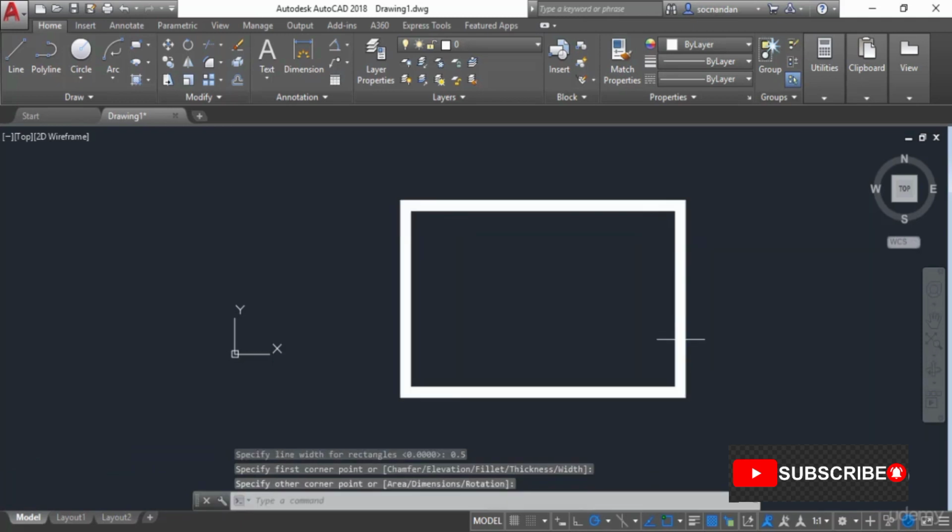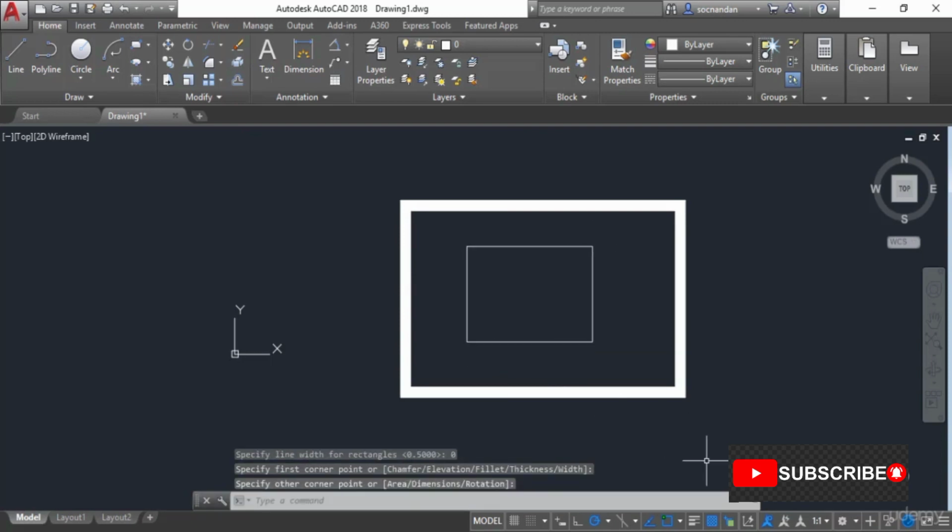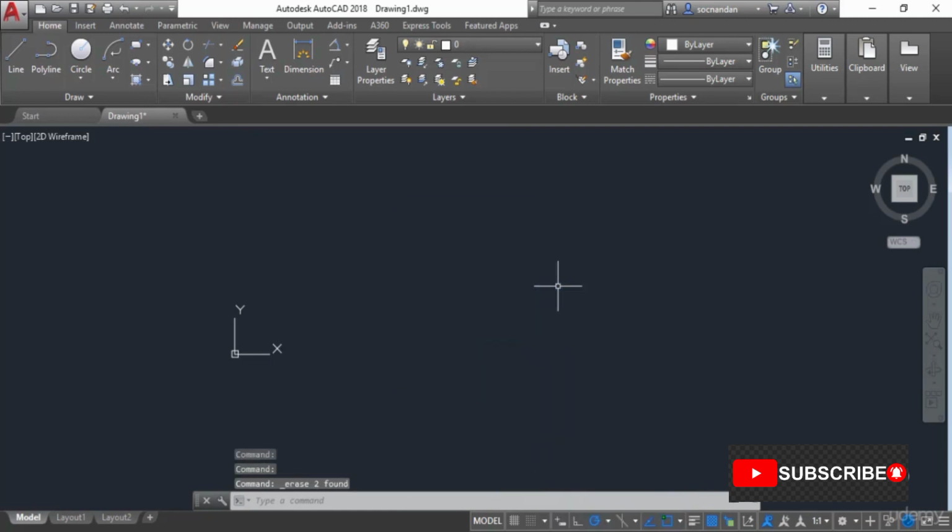And now here we have this rectangle with some thickness or some width, and we'll also learn about this polyline width later on in this course. So we again need to start the rectangle tool, select the width option and change the width value back to 0, and here we have the normal rectangle. So let's now erase it. So in this way we can make a rectangle with a variety of different options in AutoCAD.